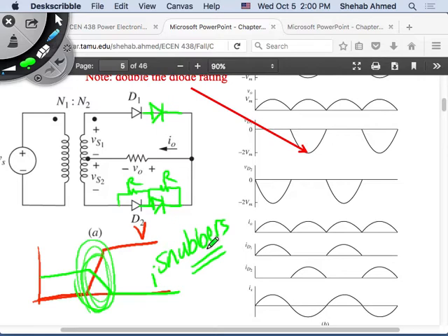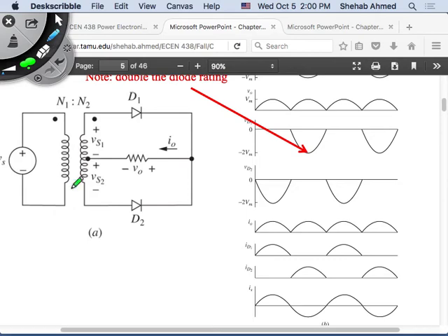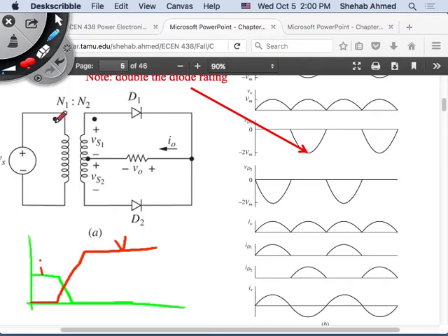Yeah. So these are circuits that you put around devices to control the turn on and turn off. In general, that's what they do. There's a section, for example, in the textbook. We will not cover that. Ideally, you would like to do what? This is current falling down, and this is voltage going up. This is V and this is I. There are some circuits that would do what? Even though you've tried to turn on the device, they would delay the rise time in voltage until here.